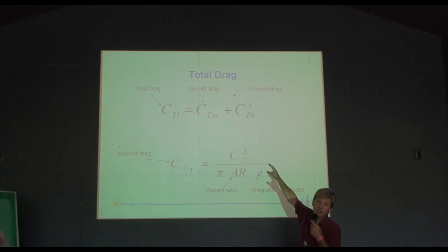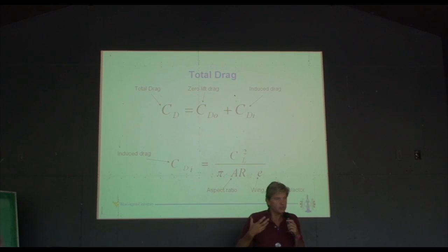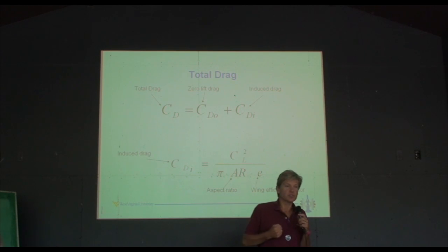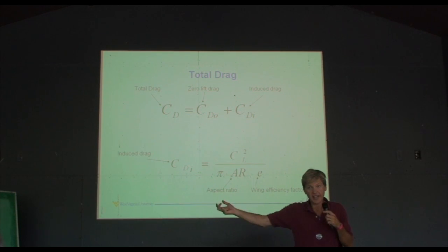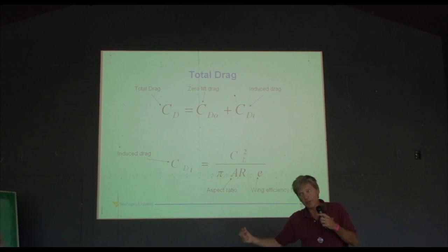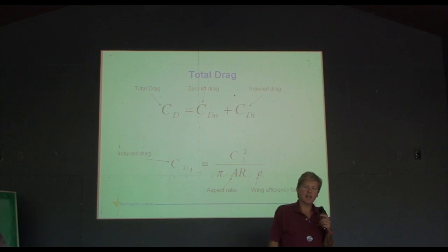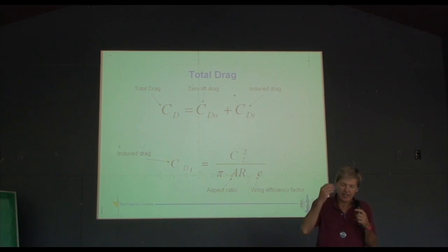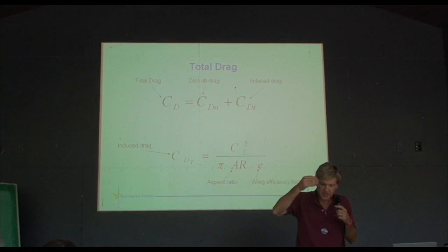Sometimes only 10%. So the induced drag is not a huge component of the total drag. Making the wing a really high aspect ratio wing will help a little, but it really doesn't help a lot. So that's why the Cherokee has an aspect ratio of 5. But it does help a little. Now, I'm trying to get you to think like the designers kind of think.